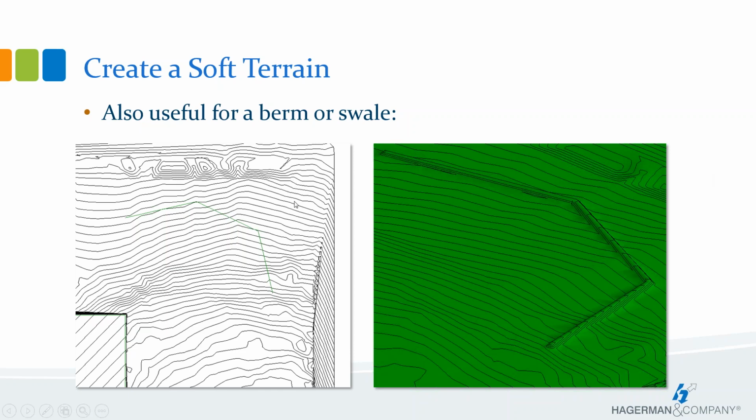One thing I think I might have forgot to mention on the initial setup that's very important is in my site plan, I always turn off the existing topography. That way, when I'm working with the tool, I make sure I don't accidentally select the existing one. So I'm only seeing the new topo surface here. Otherwise, just like in that 3D view, if I had turned off the old topography, you'd see the old squiggly lines going through my nice soft terrain, and I wouldn't want that. All right.